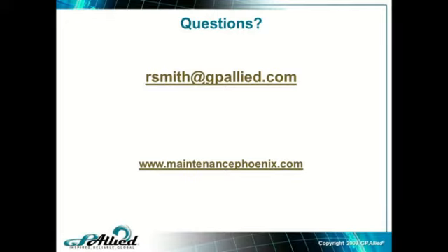You know, it's a good question. I tell people to start with, we've got to identify what a failure really is, because we have functional failures, partial functional failures, and total functional failures. What are they? We count a failure if the equipment is not operating to specification. Good question. That's what I like to sit down with senior management and discuss before we get started.